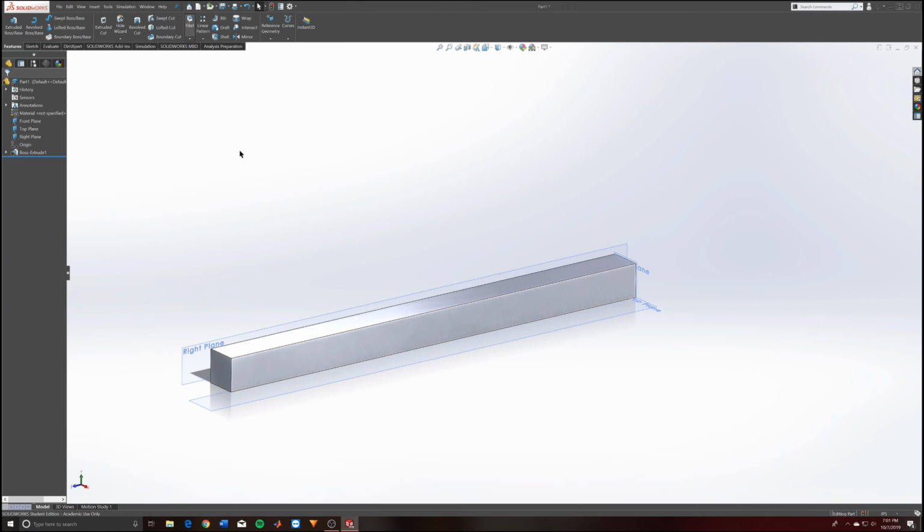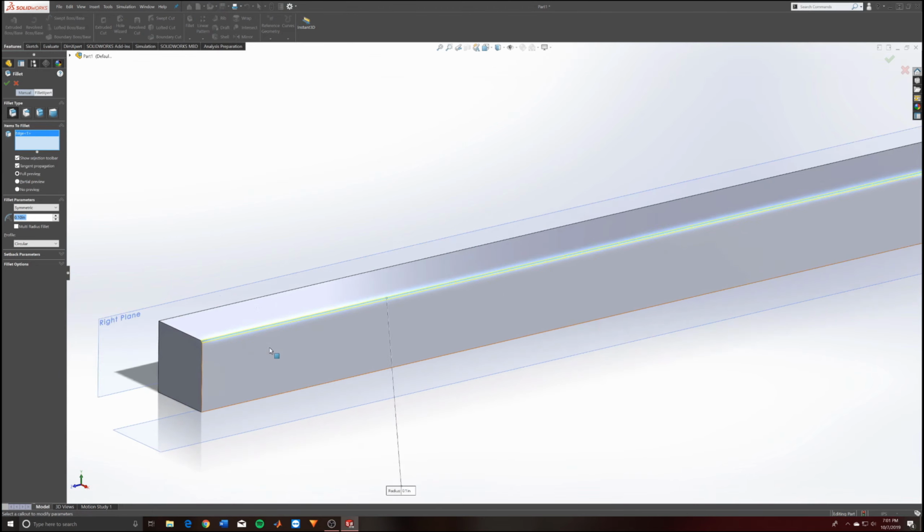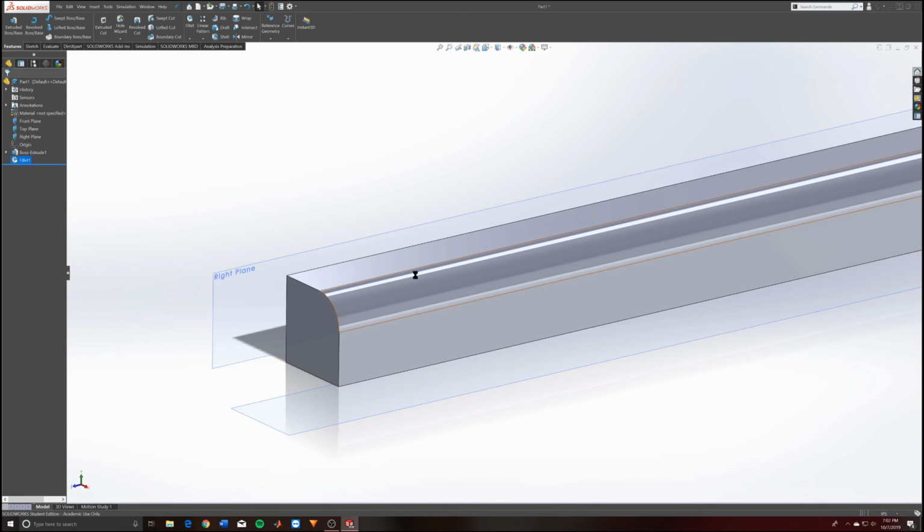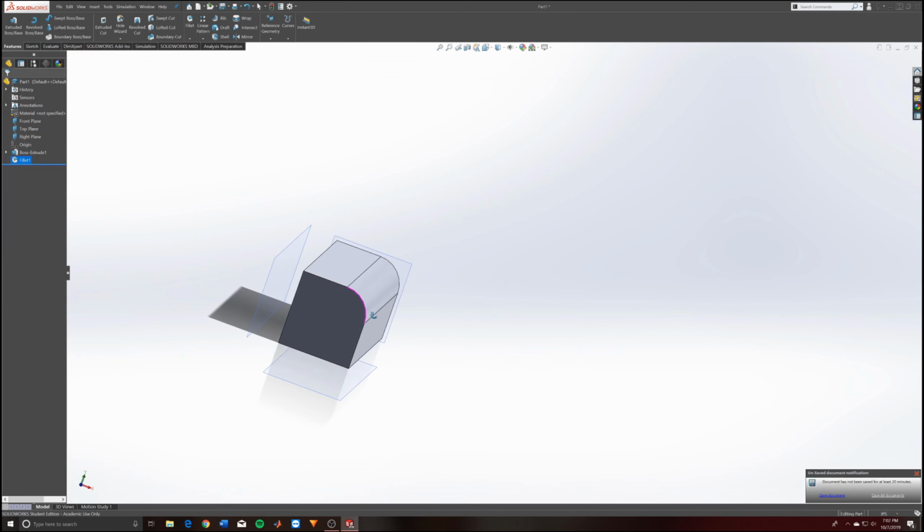So like fillet, for example, makes rounded corners, and you can't do that unless you have a part or you have an edge to round. So that's what fillet does, and here is up and down, increase, decrease, asymmetric, symmetric. You can change the type of the radius, and there are a whole bunch of other fillet options and setbacks, but a lot of the time you're just going to use the standard fillet, and as you can see, it now modified that corner.